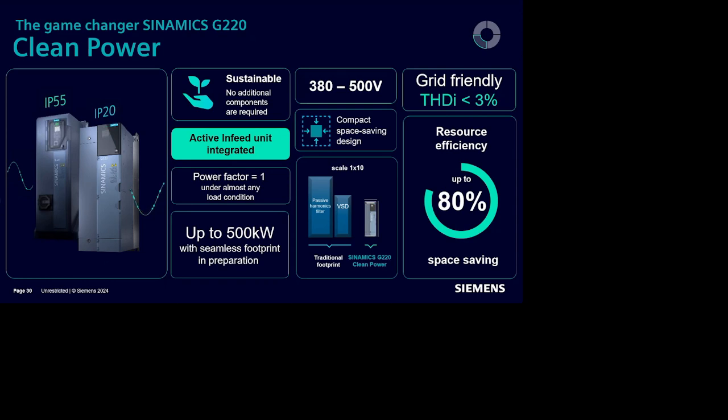And what makes this Sinamics G220 Clean Power special? Well, first of all, it has an active infeed unit integrated. With this integrated unit, which is completely inside the drive, so no external options need to be added, we guarantee a THDI, so a total harmonic distortion in the current, below 3%. And believe me, this is huge. This is a huge improvement that we have made here.